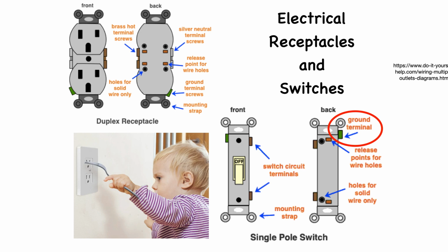Otherwise, a non-conductive faceplate should be used to avoid direct contact with the metal on the switch when operating the lights. New wall receptacles and switches will have two types of contacts: terminal screws on the sides and holes in the back. Straight wires may be used to connect to these holes in the back. The holes in the back of the device are used for inserting straight wire into the internal clamp. The holes will be labeled to indicate what wire size can be accepted.